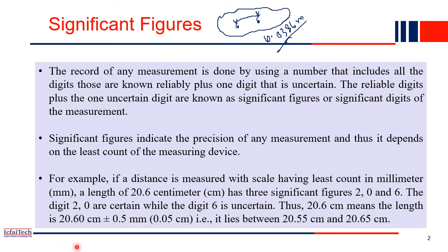It may not be exactly 10 meter, there will always be some fraction. Even for small distances there will definitely be error. If one surveyor went to the site and measured from here to here, he got 10.0386. Another surveyor measured the same distance with the tape and got, for example, 10.0388 meter.